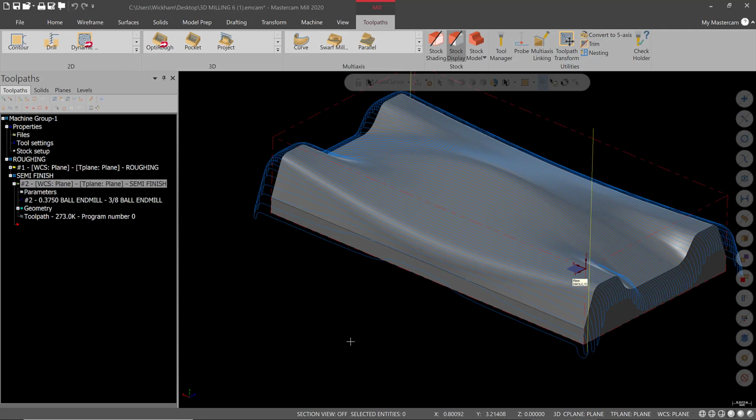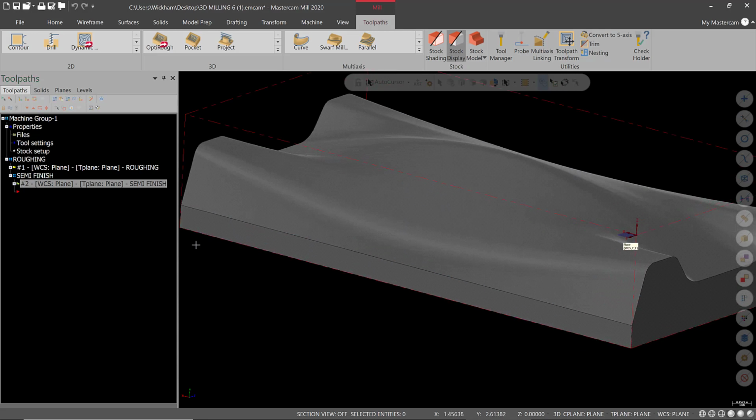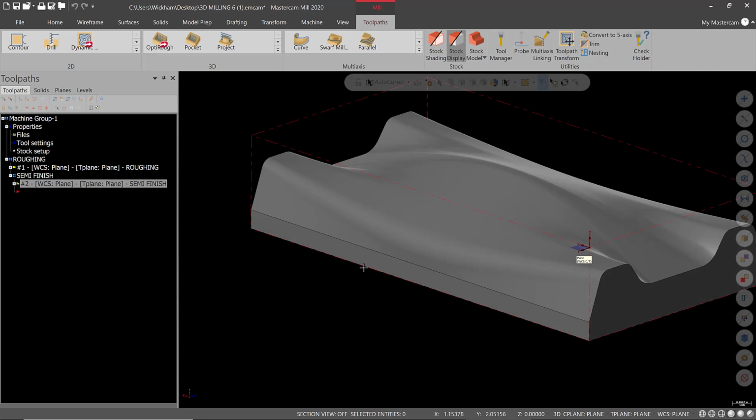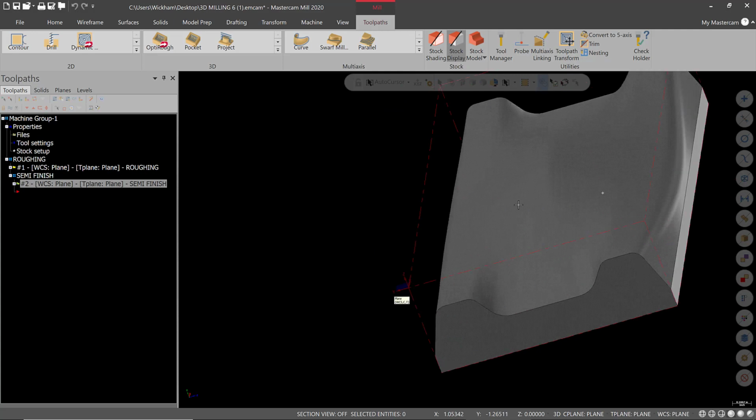Alright, let's continue on this workpiece. And again, like I said previously, we are always going to have a little bit of red right here. And there's a couple ways to get rid of that. Like I said before, you can extend surfaces. But the best way I have found, blending, I never found to be the best way to achieve this seamless straight line right here. Okay, so I turn this off. The best way to really achieve that seamless straight line would be to machine this wall and this together in one 3D toolpath, right together.